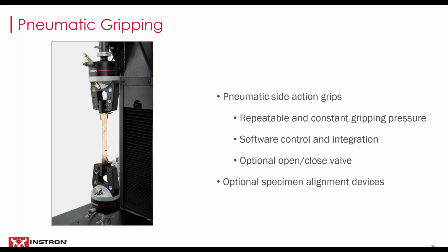Another thing that's really beneficial is our software control and integration for pneumatic grips. This isn't just related to smaller testing, but could be for other materials as well. You can go into the software and control how much pressure you're going to be sending to the grips. And the software will also be monitoring the pressure throughout your test, so it'll know if the pressure to your grips varies.